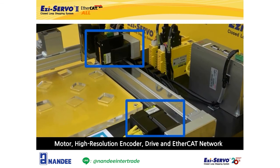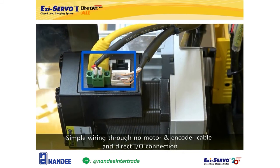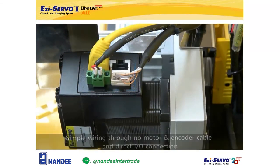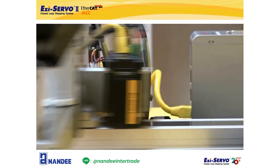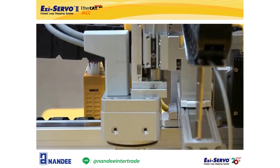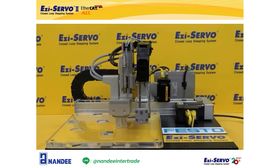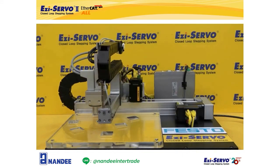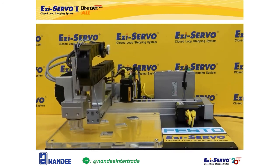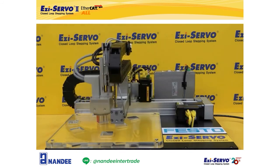Since it is an all-in-one type product that combines a motor, a high-resolution encoder, a drive, and EtherCAT network, there is no need for a motor cable or an encoder cable, and it only needs a power cable and a network cable, which saves the wiring. Also, it does not require a separate space for the drive, making it ideal for these small Cartesian robots.